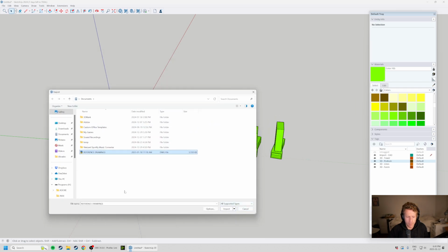But you can import CAD. You can import literally all of these files. So we've got Google Earth, JPEGs, Photoshop. For most, you can import Revit. But for most of us, I would guess we're probably either going to be importing AutoCAD or PDFs. Is PDF in here? No, there's no PDFs. You have to do JPEG. So if you do have PDFs, you have to convert them to a JPEG and import them. That can be pretty tedious, but it does happen.